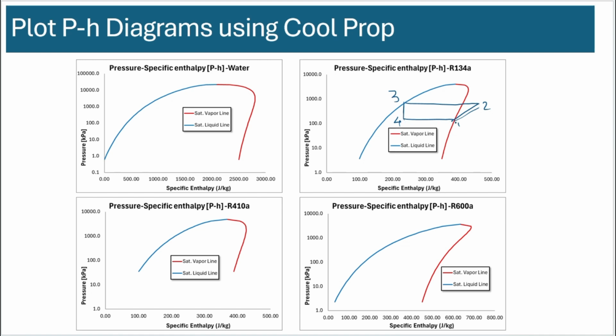So we denote the actual cycle that happens in a refrigerator on a pH diagram. The shape of this dome for different refrigerants means they have different energy efficiency, cooling capacity, etc. So you could compare a lot of different refrigerants and do a lot of modeling on how they would compare to each other purely from a refrigerant standpoint using their phase properties and pH diagram.